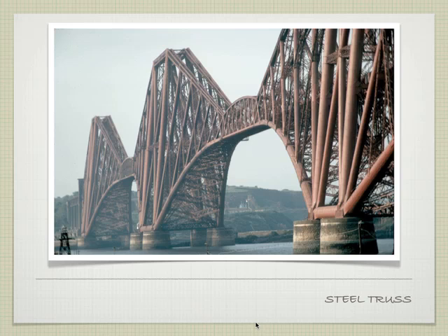Right. So it's a bit of a misnomer. The reason that I'm trying to call it non-working steel is to tie it together with the idea of concrete when we remove the non-working concrete. In a plate girder, it's a little bit more complicated. I'm glad you brought it up because at least we can talk through it. The plate is acting with an infinite number of these diagonals, right? Likewise, an infinite number of the diagonals in the opposite direction.